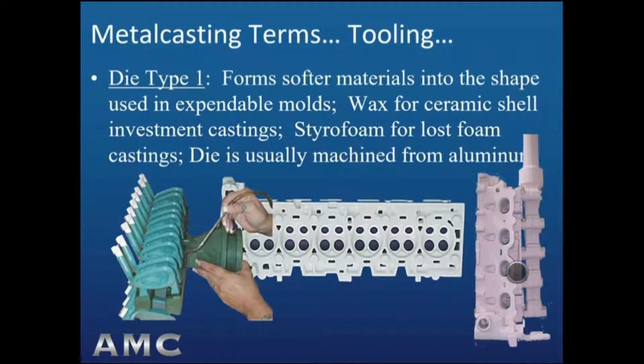Dies. Die type 1 forms softer material into the shape used in expendable molds. Wax for ceramic shell investment castings, and styrofoam for lost foam castings. The dies are usually machined from aluminum. So at the lower left, we see an operator wax welding golf club patterns to an investment casting tree, and at the center and at the right, we see the lost foam patterns made from a die for an engine block, or those are engine heads.